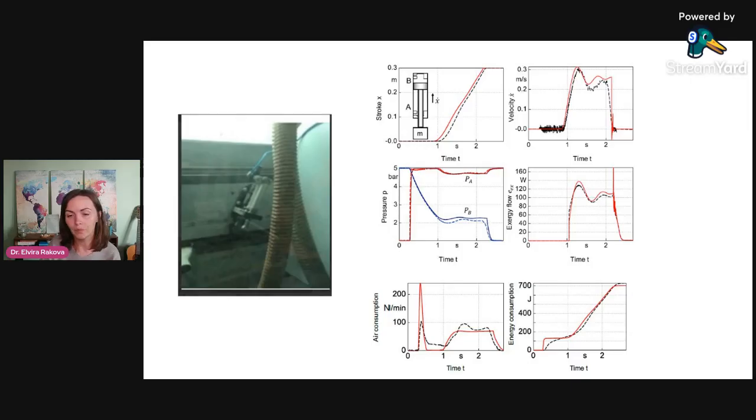So meaning that first we need to fill up all the volume of the pipe, the dead volume of the cylinder, and then start filling the cylinder itself so it starts to move in order to perform this thing. So you have the diagrams. This is the stroke of the cylinder. You see that the cylinder starts to move just from A to B, from 0 to 300 millimeters. This is the stroke of the cylinder.